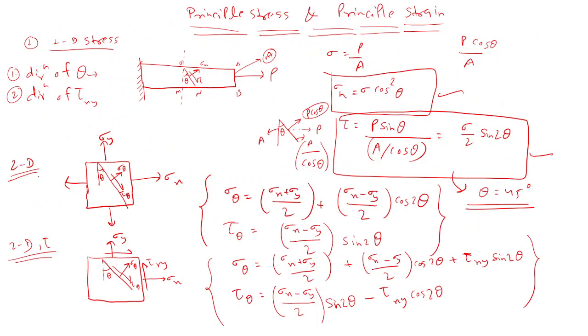So this 2D stress, what is it showing? This 2D stress is in the normal loading, sigma x and sigma y. This is the principal loading, right? No shear stress in that plane. What is the principal plane? Those planes where no shear stress is acting, right? So in this 2D loading, it is showing the principal planes, right? Clear to everyone or not?